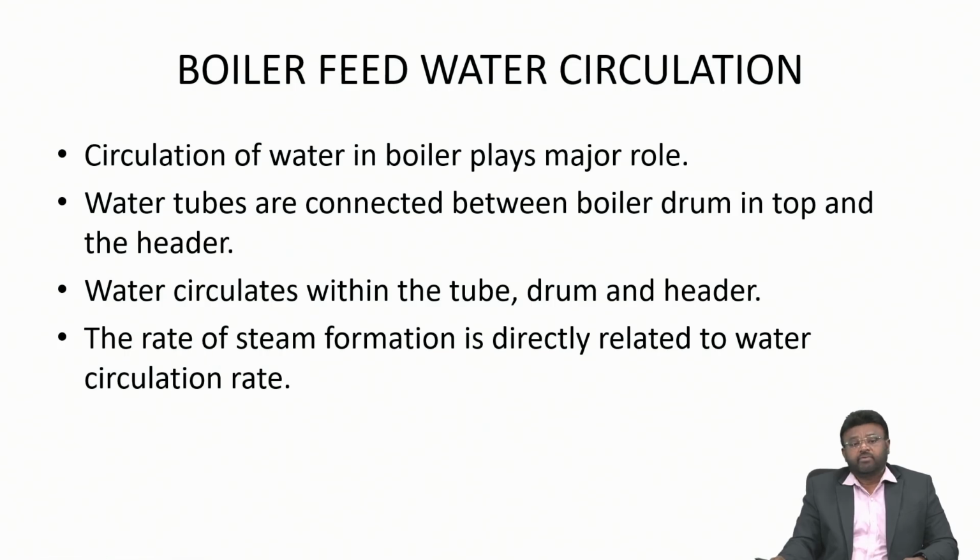In addition to that, we have another important aspect, boiler feed water circulation. This is necessary because the water is to be sent to the boilers at defined specifications. If we are unable to send this water to the boilers with proper flow rate specifications, then it may sometimes lead to the blast of a boiler.